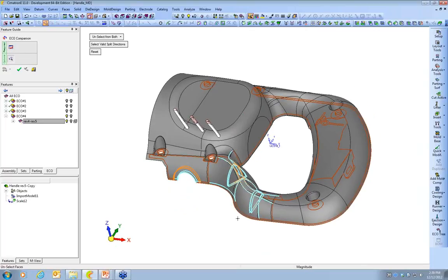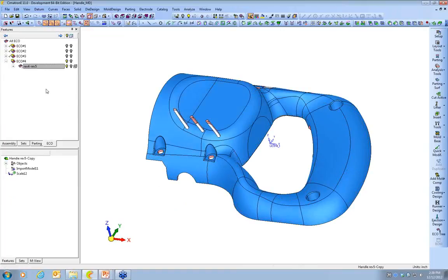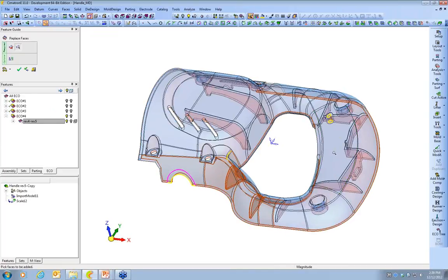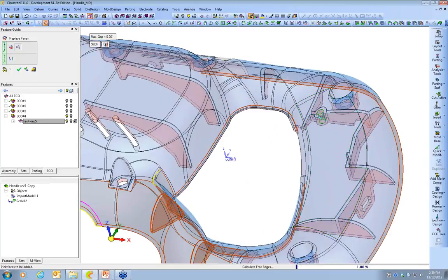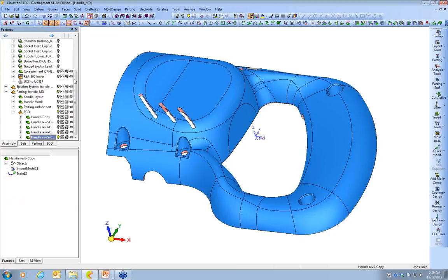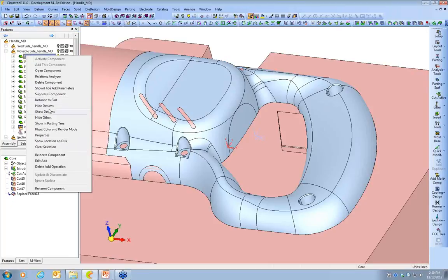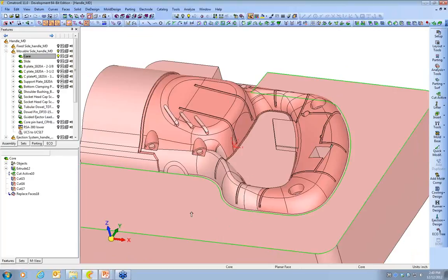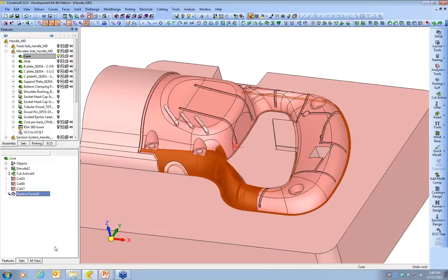So now the results we're seeing are only the ones applied to the bottom set, the core block set. Once again, we're going to use replace faces, and the receiving part, which is the core block this time, is going to get this new data. Okay, the revised data is clearly in place. It's added as the very last feature in the tree. The goal of avoiding any feature regeneration is completely achieved in these cases.